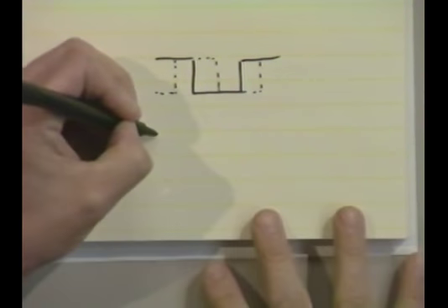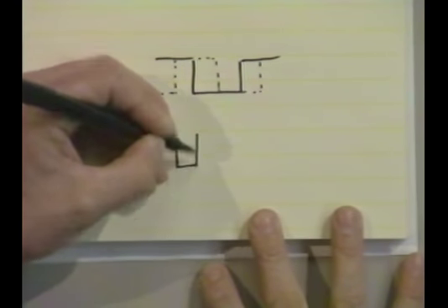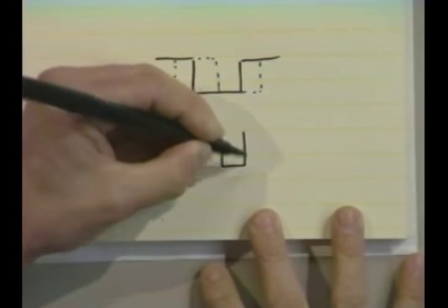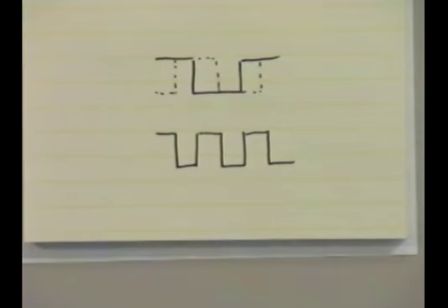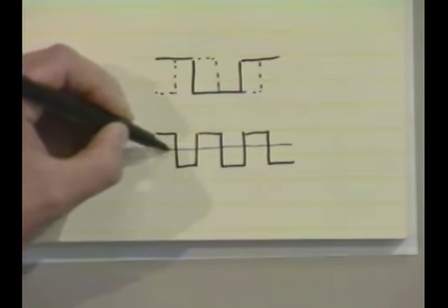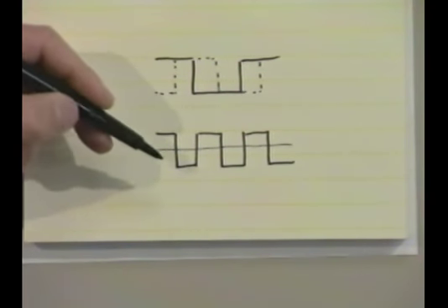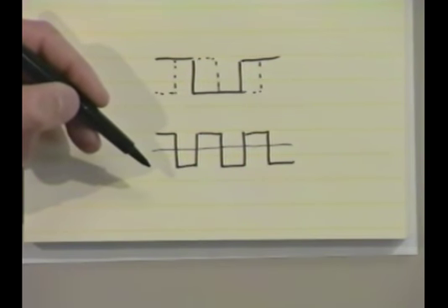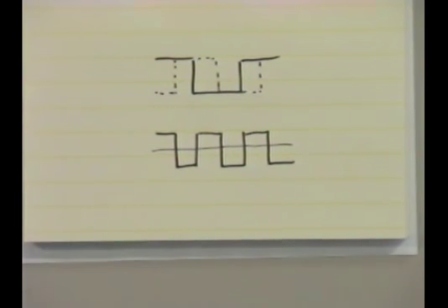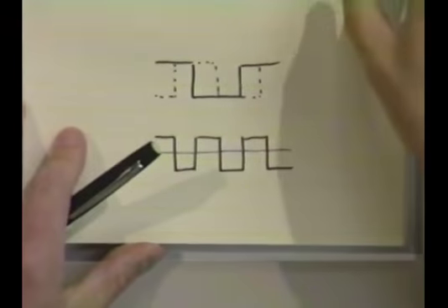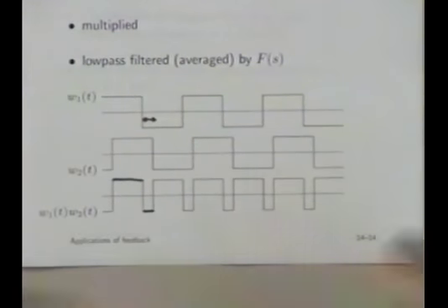Yeah, you know what you get is you get a perfectly regular square wave at twice the frequency. Okay? And what is the average value of this thing? It's 0. Okay? So what we've already seen is pretty obvious, right? That when you take the product of two square waves at the same frequency, and then you look at the average value of that signal.